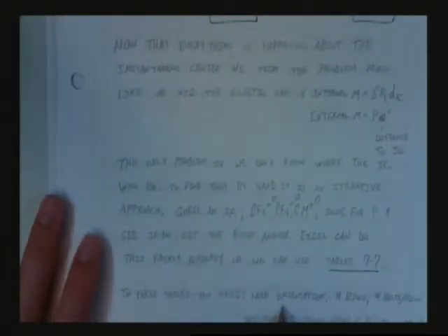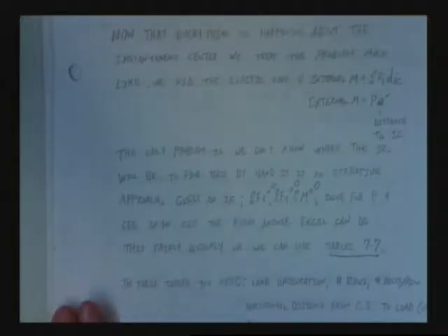But in these tables, you need the load orientation, the angle that the load is applied at, the number of rows of bolts, the number of bolts per row, the horizontal distance from the center of stiffness to the load, and the bolt spacing. So if you know all of these things, it's cake. Okay? It's cake. Now, this is really, really important.